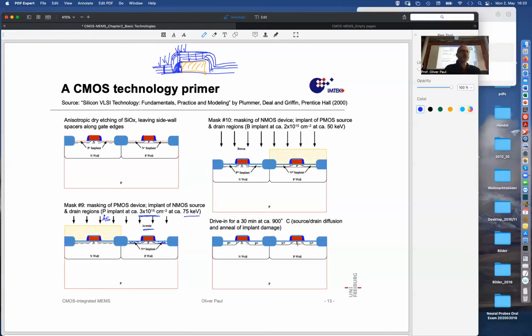The p-n junction doesn't form now here at the end of the high dopant region, but we have this gradual transition into the lightly doped region, and then the junction extends over a larger extent into the lightly doped drain, and the peak electric field is lower thereby.